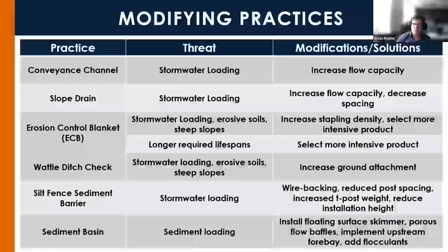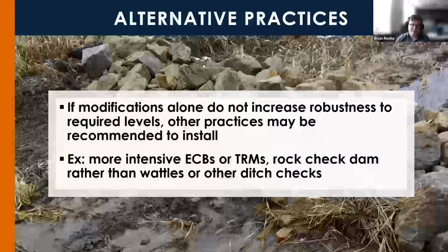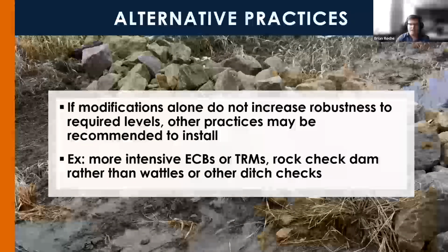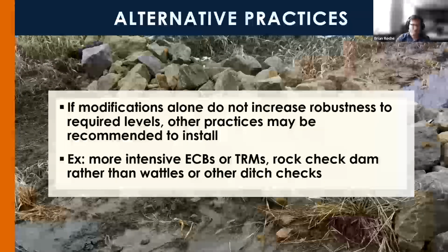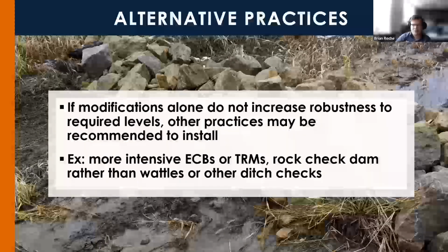So if you're unable to lower risk to acceptable levels through modifications alone, other practices that are inherently more robust may be recommended, such as using a rock check dam rather than a wattle or another ditch check practice.